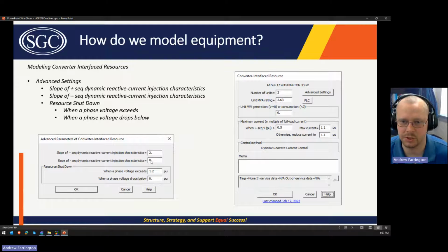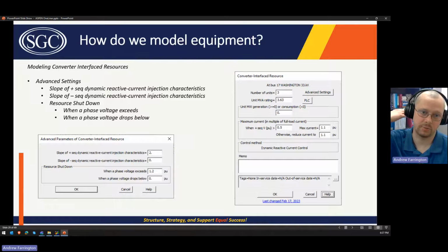And this is great for us protection engineers, as I'm sure you'll learn about in the distance protection lectures. The negative sequence current is really important for determining fault direction. A lot of times with the directional elements, if the source behind you has a lot of type 4 machines, you don't have a negative sequence source behind you, and so you can't use directionality unless the fault is towards the solar farm.